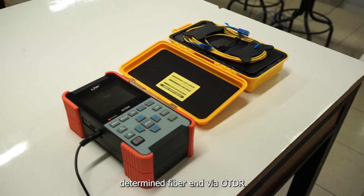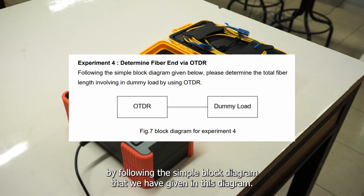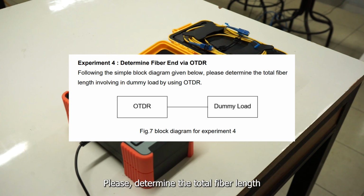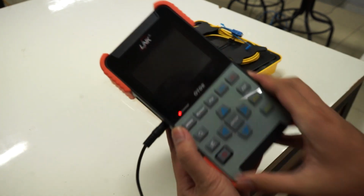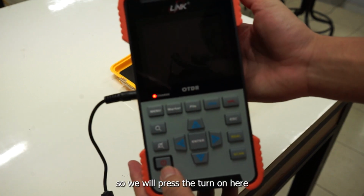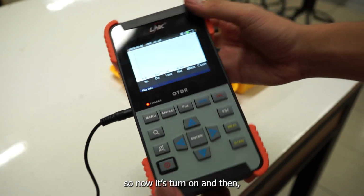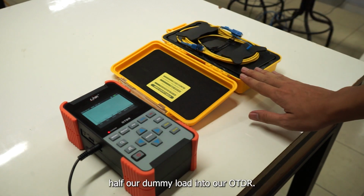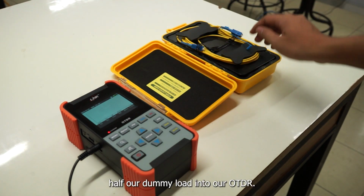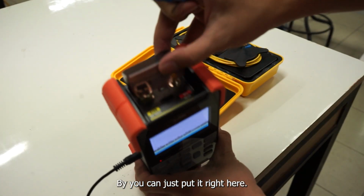Experiment 4. Determine the fiber end with OTDR. By following the simple block diagram that we have given, please determine the total fiber length involved in the dummy load by using the OTDR. We will turn on the OTDR first, so we press the turn on button here. Now it's turned on, and I'm going to put one side of our dummy load into our OTDR. You can just put it right here.